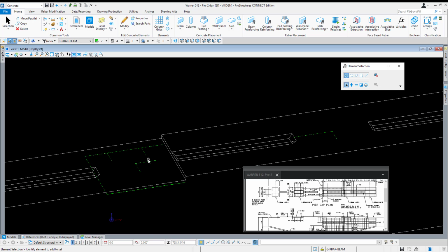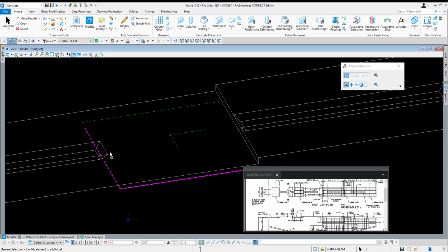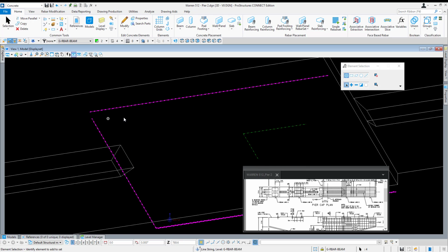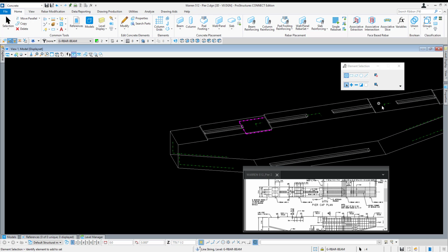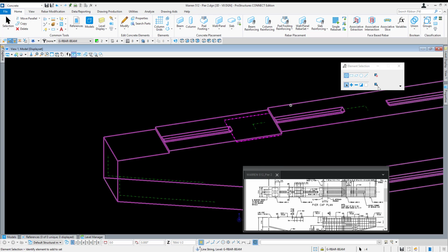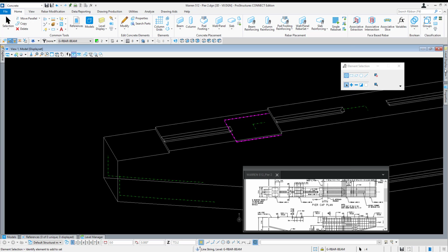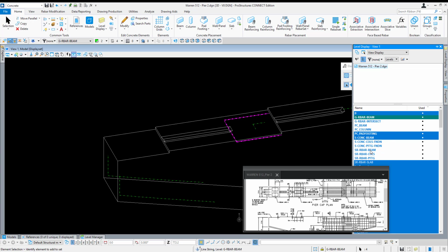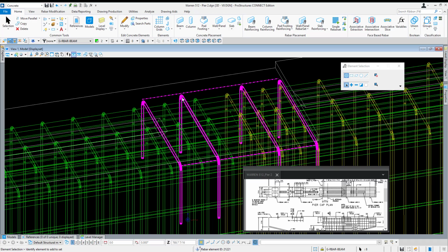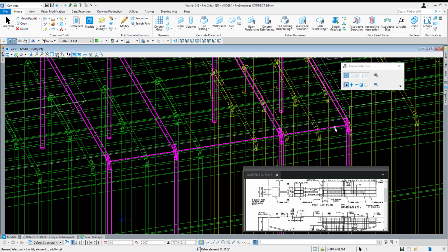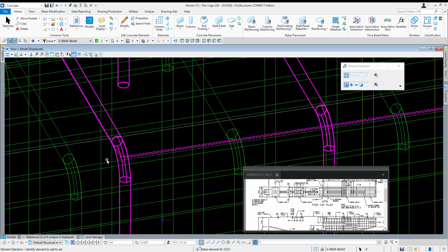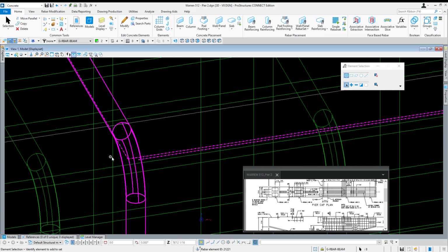Now, before I turn my beam back on, what I'm going to do is get rid of stuff I don't need there and highlight my guidelines that I want to use to copy, right? Because I'm about to copy this to the other locations that I already have little points put for. So I'm going to highlight my guidelines there, turn my beam reinforcement back on, select the beam bars. It's like we might have lost our lower bars during the copy there.